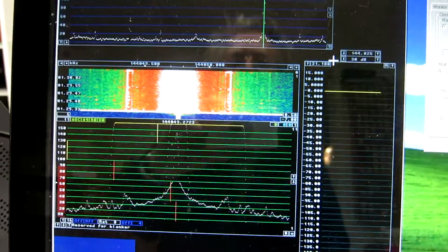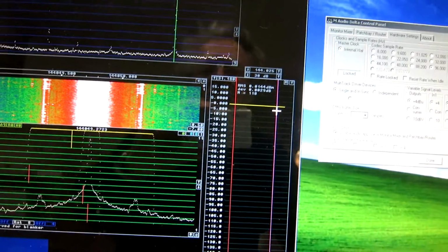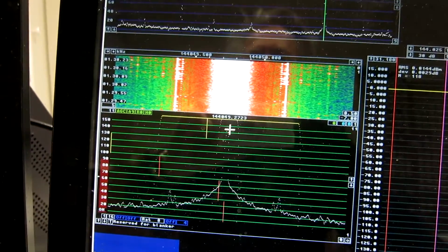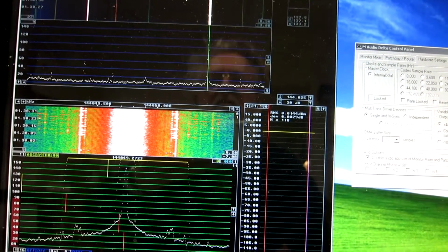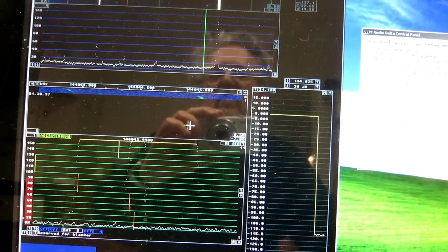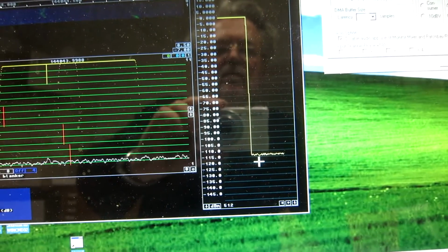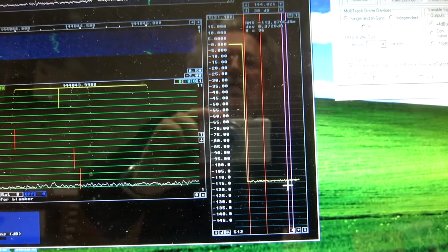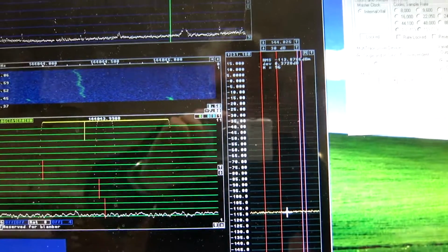Here is the screen of the WSE converters, and I do the same here. The carrier is at 0, bandwidth 1 kHz, and I step 5 kHz down. We are at 049 in this scale, so I want to go to 044, 5 kHz. 044, something like this. And here the noise floor is, well, I have to wait. Minus 113. That's almost the same as we had with the signal off in the Perseus.